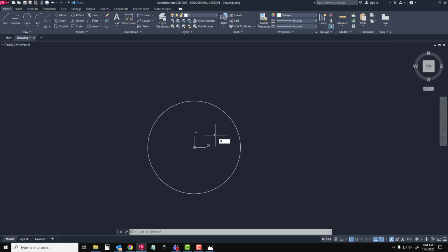So I'm going to type in user coordinate system. I don't want it to be on, so this brings up a little sub-menu, and I'm going to click off. So now that's missing. So that's good. So now I kind of got a good view of what's going on, and I'm not going to have an extra stuff printing. So I have another circle, so I'll type in circle.